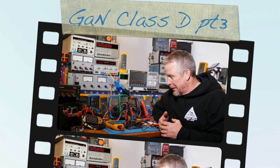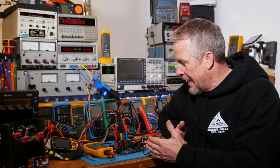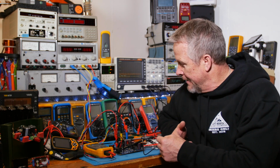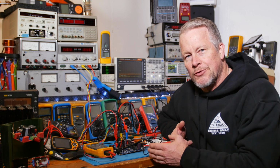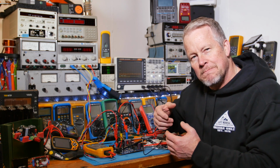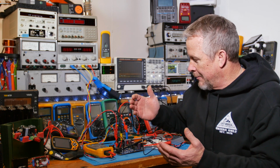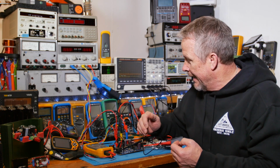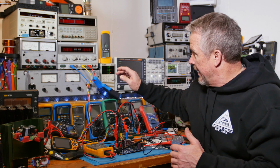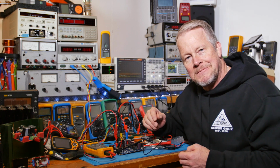Alright, so today we're going to do the third in this series on this Class D audio amplifier. It has GaN FETs in it. Today we're going to look at the distortion across the audio spectrum. First we'll inject a 1 kilohertz signal and see what we get: harmonics, subharmonics, whatever, and see if the noise floor jumps up. Then I'm going to show you how to sweep the signal so we can look across the spectrum and see what it looks like.